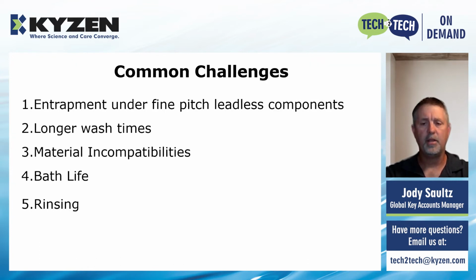So some of these common challenges: you're going to have entrapment under these fine pitch components, and it's important to get these flux residues or other ionic contaminants out of there. In some cases, there could be cleaning agent stuck underneath there. You could have longer wash times, material incompatibilities, and then, of course, bath life, which we think is really important.